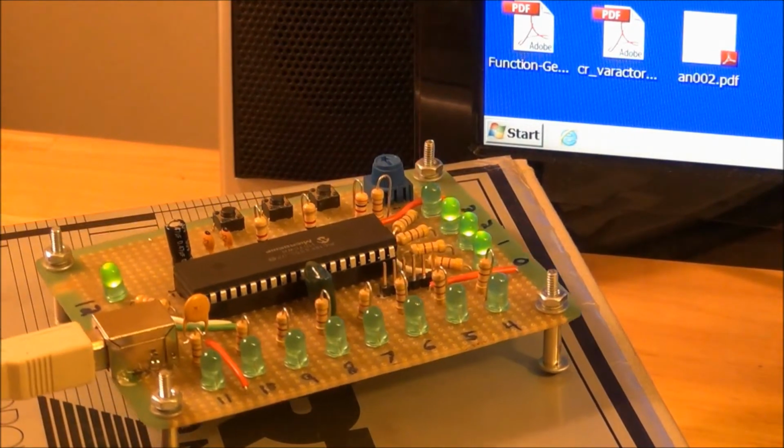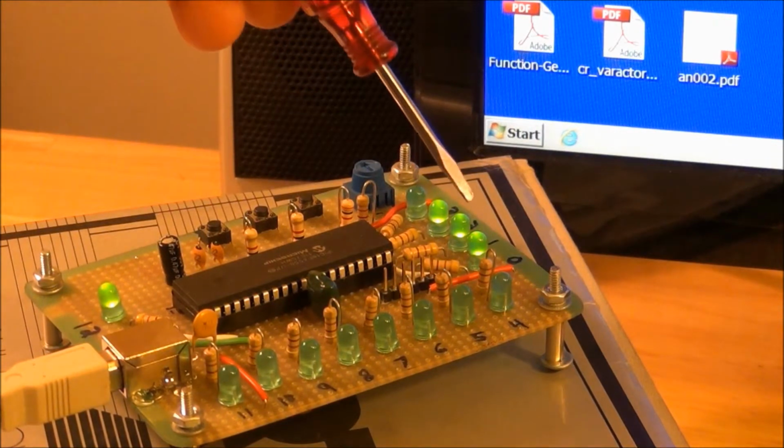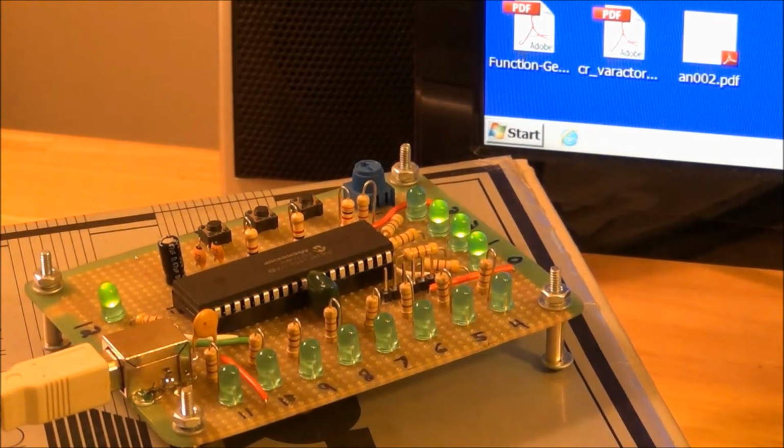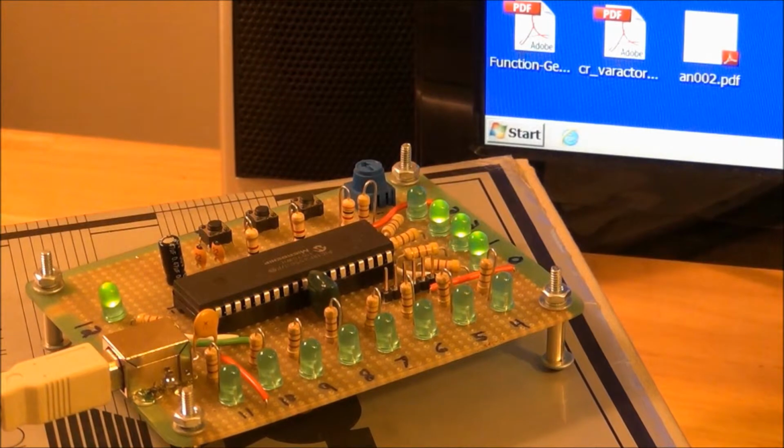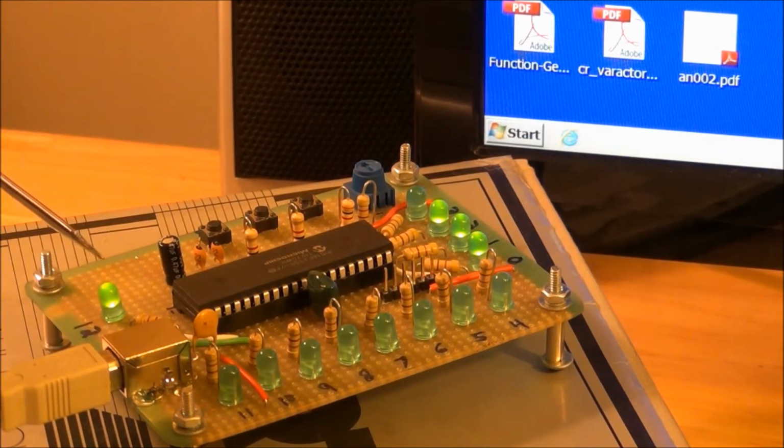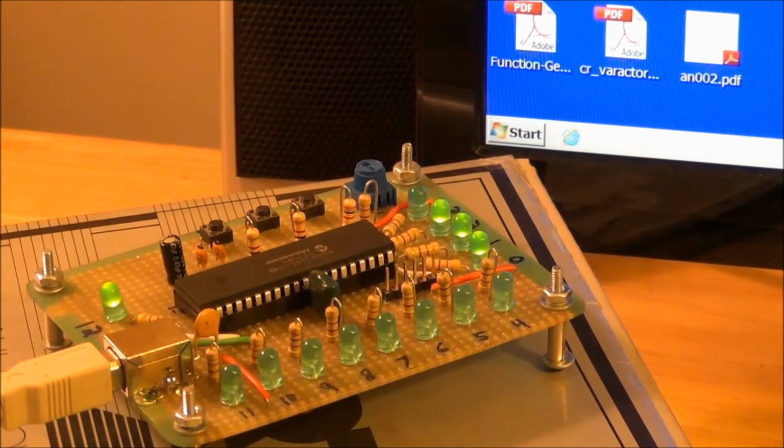So the way our board is set up here, LEDs 0, 1, and 2 indicate the states that we saw earlier in main.c, stepping through all the way to configured. And this LED at the bottom of the board here, 12, that's just a power LED. Anytime the computer is powering the board, that LED will be on.